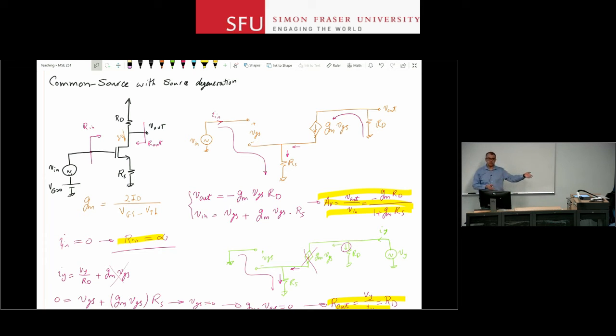And for the other two common amplifier stages that I'm going to talk about, I'm going to stick with the BJT, which is a little bit more complicated, but the MOSFET one is going to be very, very similar. You just replace RC with RD, RE with RS, and if we have a gate resistor RG, it replaces RB. So that's that.